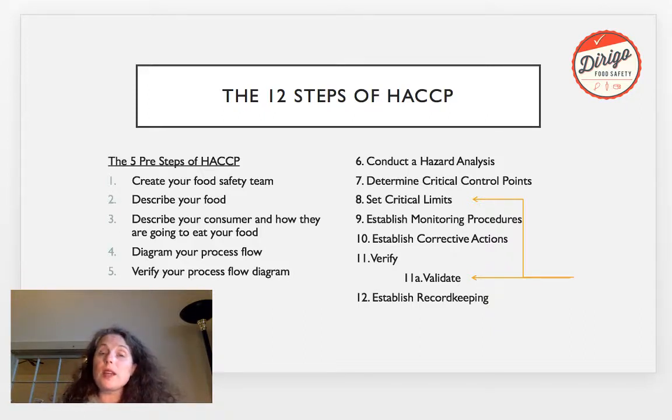All right, so then the next step is what we call a hazard analysis. We take all those steps of the process flow diagram and we write down what can go wrong with physical hazards, chemical hazards, or microbial hazards at every single solitary step. FDA folks have to do that with ingredients too, okay? Sounds complicated, but if you do this step right, the rest of this is fairly easy. All right, and then we decide what are the critical control points.